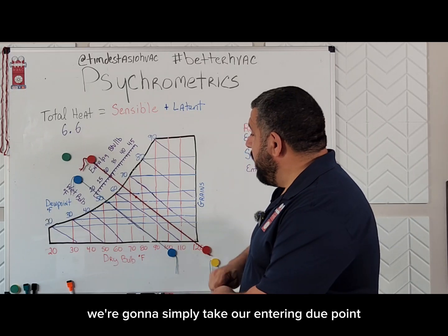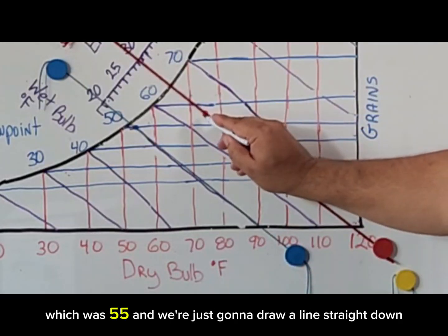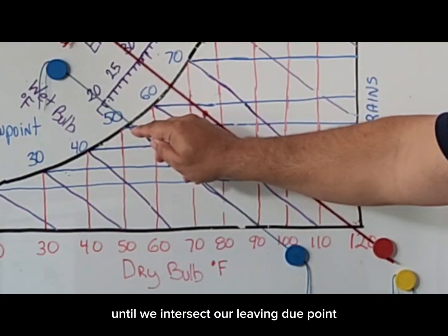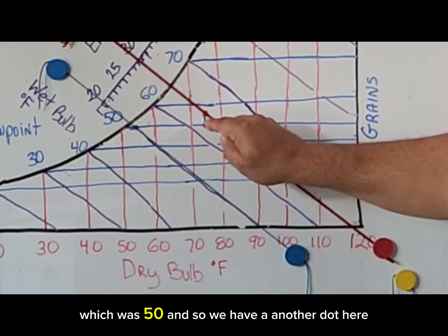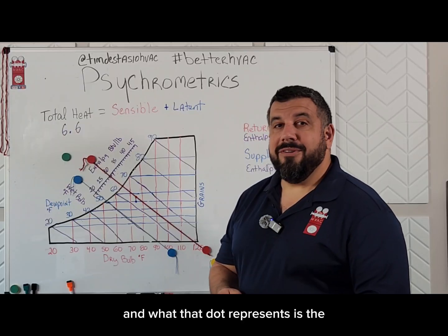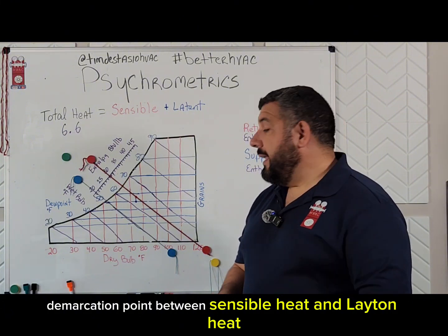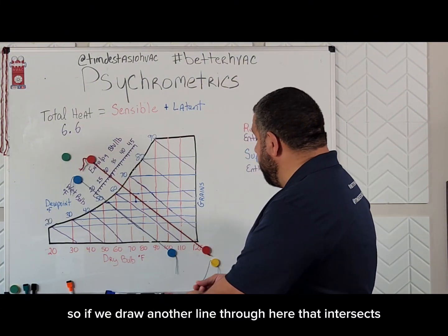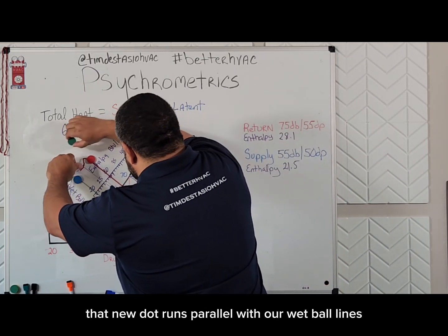We're going to simply take our entering dew point, which was 55, and draw a line straight down until we intersect our leaving dew point, which was 50. And so we have another dot here. And that dot represents the demarcation point between sensible heat and latent heat.